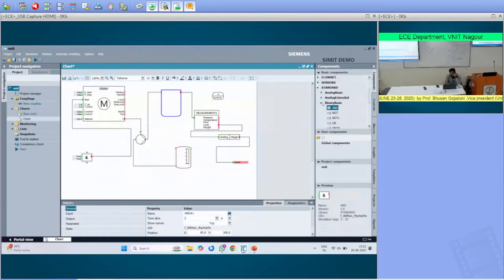Basic programs, conversions, multiplication and compare values, all of that we can do here, because the PLC will send 4 to 20 milliamps. For that we need to convert the integer values to analog values. All conversion-oriented things are possible. Basic-oriented standard libraries are also there, through which we can convert all the data inside the platform itself.